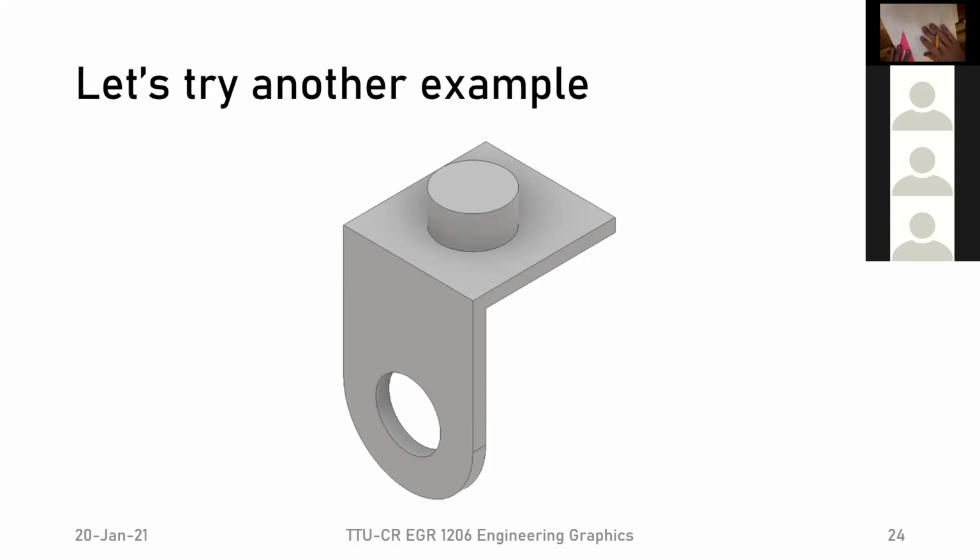And then we have to do it in the other direction as well, because it's a circle, and we'll learn about that, this is the circular view versus the rectangular view, when we do dimensions. Again, we want to have one here, and then the longer dash goes all the way across the object. This one is a little bit shorter than the other ones because there's no other half circle there. Okay, so this would be now the center line for the bottom circle.